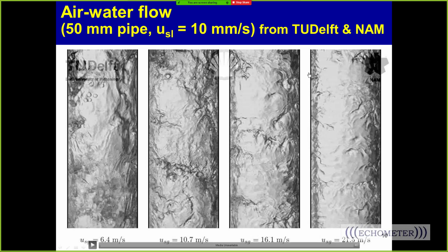The question is, over here we're liquid loaded. Liquid loaded starts around 10 meters per second, I think. So there's a liquid level in this well, and there's not one here, but there might be mist. And if there's not enough liquid being carried by the gas, you'll see through the center of the tubing and not see a level until you get down to the end of the tubing, probably. So the amount of liquid is important. The more liquid you have on a flowing well, the less likely you're going to be able to see through it, because it's going to be gassy liquid all the way to the surface, or a mist all the way to the surface. Okay.